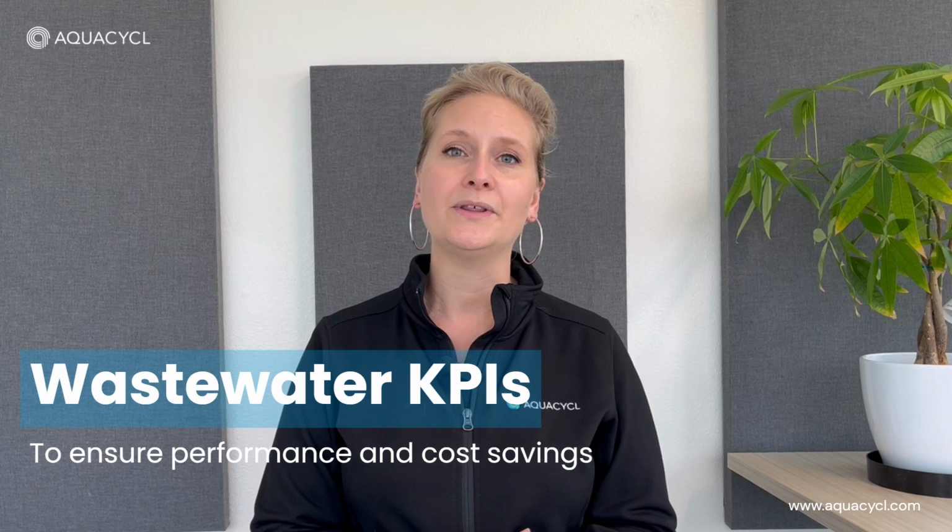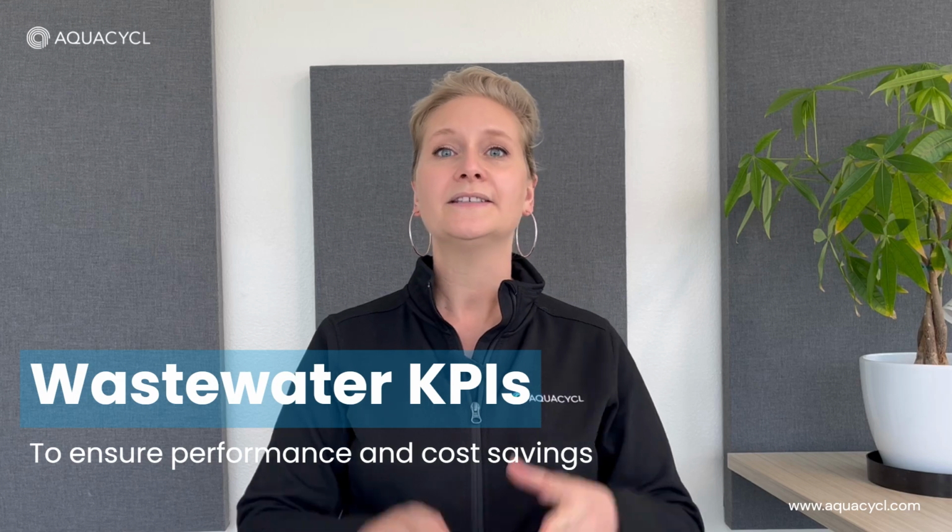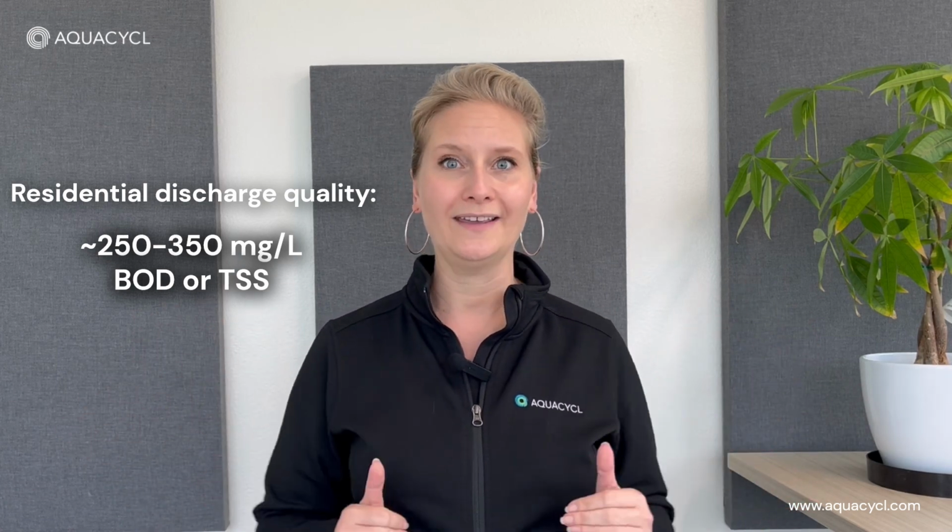So today we're going to talk about how you set your KPIs so that you can reduce cost, meet compliance, and ultimately simplify your wastewater management. Many clients, especially industrial clients, have the impression that they are required to hit residential discharge quality whenever sending to a collection system. What that means is that your threshold of concentrations of biological oxygen demand or total suspended solids has to be right around 250 to 350 milligrams per liter. Well, yes, that is the residential cutoff. And of course, your utility would love it if you can get there.